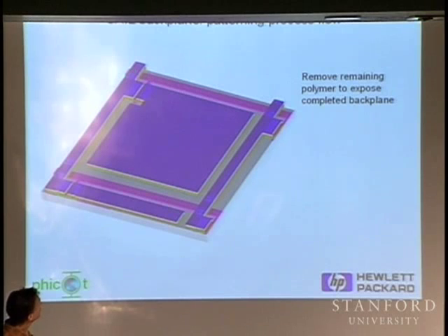That's all you need to drive e-ink. It's pretty much all you need to drive liquid crystal. So you have a hold capacitor, you have a transistor, and then you have a cross-point addressing scheme where you have a select line and a data line going the other way.